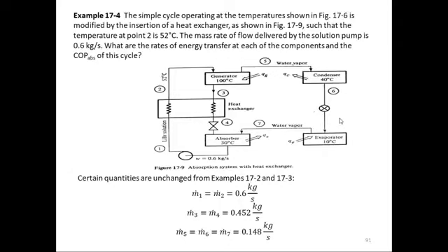So this heat exchanger did not affect the pure water side, that is, it did not affect the condenser and the evaporator. Previously we had H3, H4 and H7 here, so those will be H5, H6, and whatever value we found before from the table, we are going to use the same value here, because these are not changed. Only the values at 2, 3 and 4 will change, so we have to recalculate those. Otherwise these are the same.